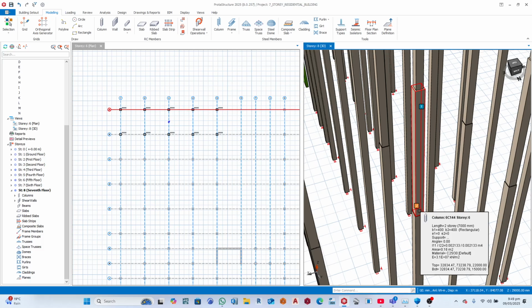That axial load, if it's 10 kilonewtons, whatever axial load has been generated from the floor on the 7th floor, plus that one. So if we have from the 7th floor another 10, so we have 10, 10. The 7th floor to 6th floor column will be handling 20 kilonewtons. Then the 6th floor to 5th floor will be handling 30 kilonewtons, and so on, until by the time you're at the bottom of the foundation, you have like 160 kilonewtons, or is it 80 kilonewtons, which is being taken to the foundation. That's how they behave.